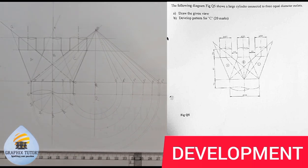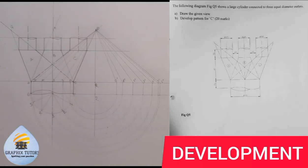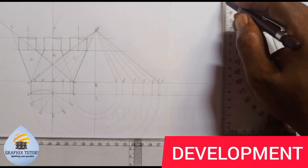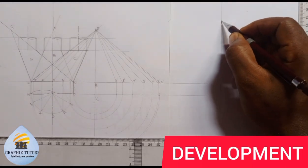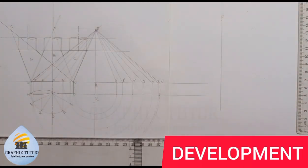So the next thing that we're going to be doing here is to draw out what? The development of it. So now I can pick it up from anywhere, right? At any given point, I'll just draw a line. Let's see, I'm picking it from here, and I'll draw a vertical line this way. So I'll pick from the top of the line, probably here. I'll make it to be my point P, because here is P. That represents my apex point.